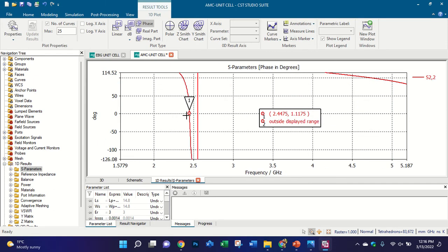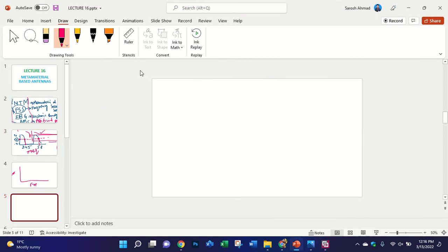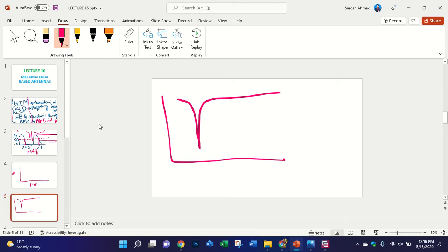Why must it be 0? If you talk about the other angles, it will not reflect, like you in reflection coefficient that reflects at the desired frequency band. If you have S11 of the antenna, and it is reflecting at, suppose, 2.45 gigahertz, and you are using the MTM or any metamaterial technique with a 0 degree reflection phase, then it will not reflect this one.